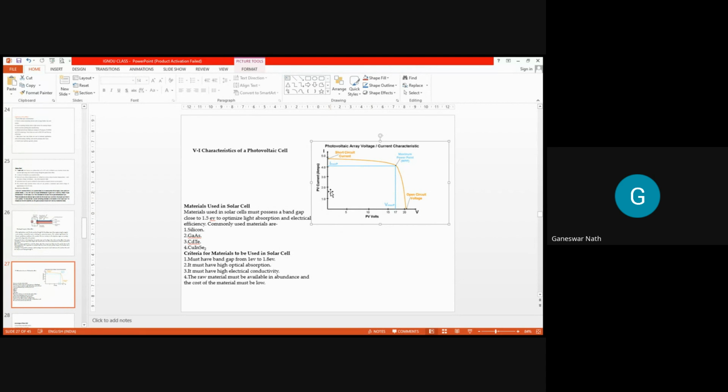In a solar cell, even if light is not incident, you can get some current due to some internal mechanism. Internal mechanism means there is random movement of electron holes inside the semiconducting material, so it is always in a recharging or active condition. Then even when the voltage is zero, you can get some dark current. So even at zero voltage there may be some potential and some current.